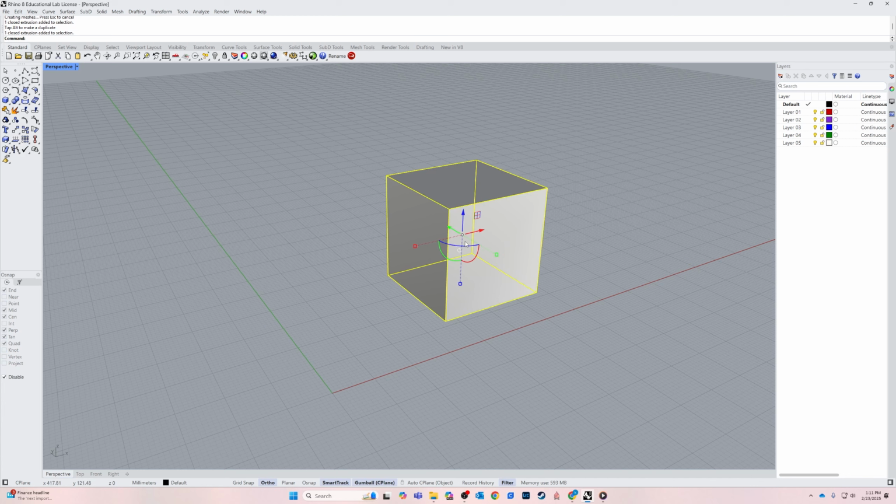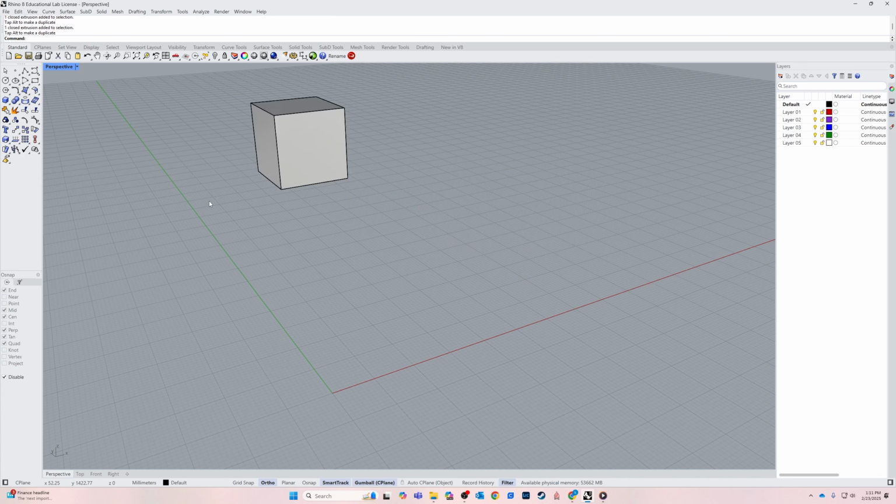The next one I'm going to do is the pyramid. Or actually, let's just type pyramid. Pyramid, yes. And how many sides for my pyramid? I'll do 3, enter. And you can see when you drag out on the pyramid with ortho on, it locks it in.